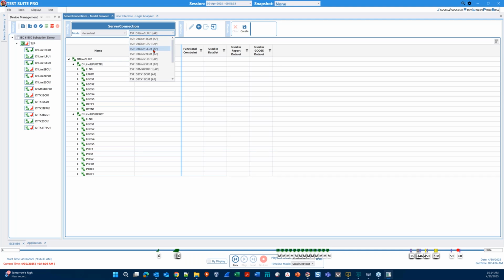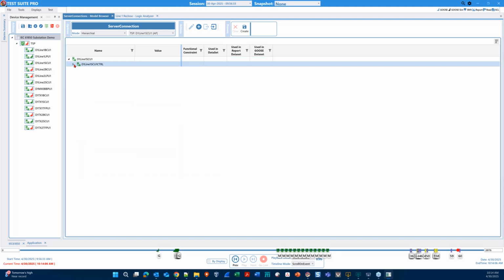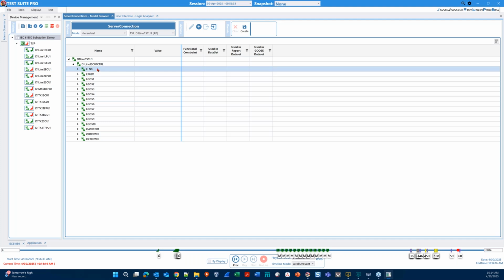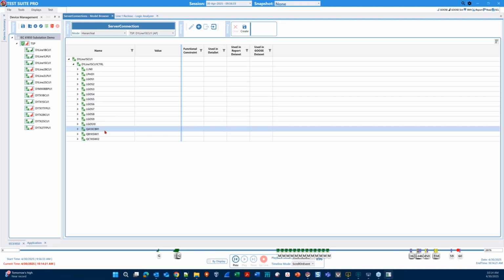Finally, switching over to the Switchgear Control Unit. This is the last IED in this particular bay. Here is where we're actually going to interface with the specific conducting equipment. This IED only has a single logical device, and the logical nodes that I want to draw your attention to are down here at the bottom.